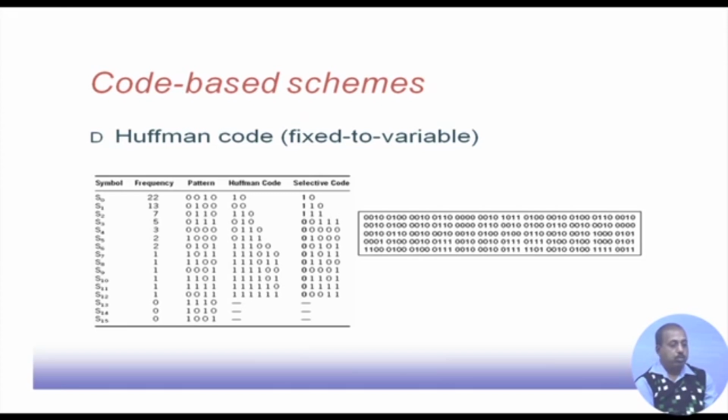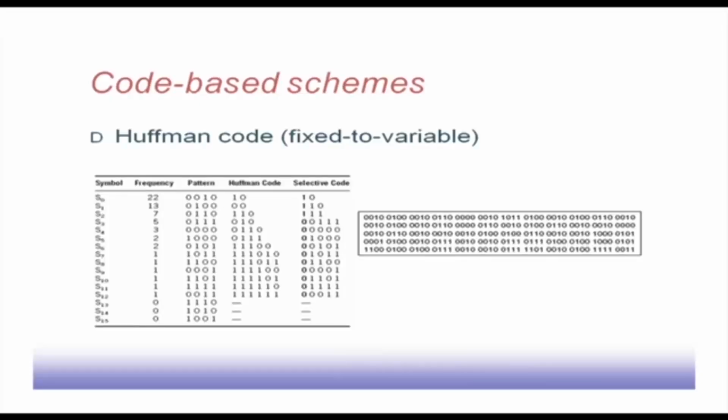In selective Huffman code, it can give rise to further compression compared to the normal Huffman code, and the second advantage is that the dictionary size can be drastically reduced. So, the designer can do a trade off. If you do not want to spend much area for holding the dictionary, then the dictionary size can be reduced, and the dictionary will accommodate only the first few most frequently occurring patterns. The compression will suffer, but that may not be that high, because the most frequently occurring patterns are definitely covered by the coding.